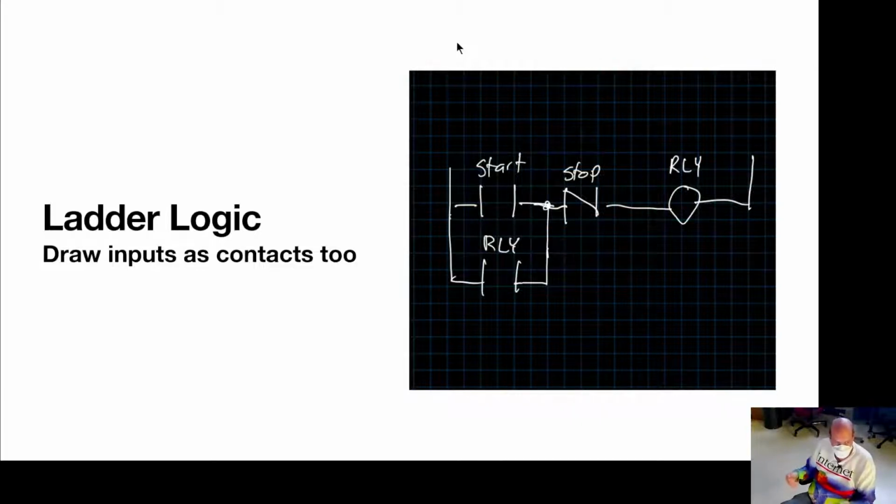For industrial automation, you would have a whole number of relays actuating different solenoids that would actuate air cylinders or whatever else, driven by sensors in your system and so on. So your PLC allows you to simplify your control cabinet and make it more flexible as your system gets larger, and eliminate a whole lot of parts in your control cabinet that used to be individual components.